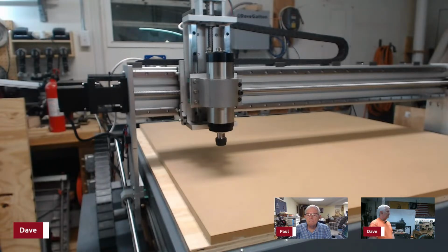So once I move that back and forth and then tighten those up, that's the same procedure that they do with the Avid when you're putting one of those things together. That's really where I got all that information from. They had a block that you set on top and fasten it and then clamp that top one to it. You tighten it up, and then the other one you leave loose. And as you're moving it back and forth, you tighten it up when you're next to the bearing. That way it's good and parallel.